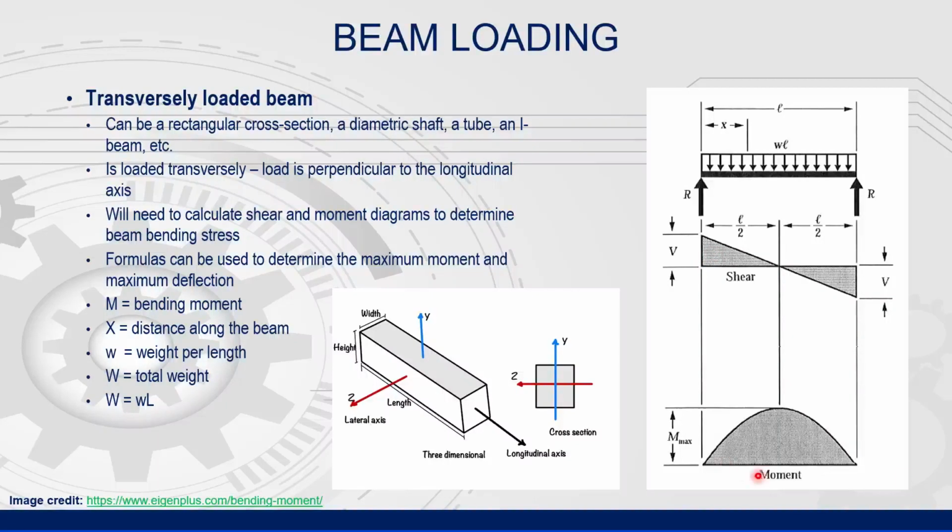Below the shear diagram is the moment diagram. The moment diagram results as an integration of the shear diagram. It also progresses along the length of the beam from left to right, and you will notice that the moment gradually increases from 0 and maximizes at the same location where the shear diagram indicates 0. Then the moment diagram generally decreases and comes back to 0.